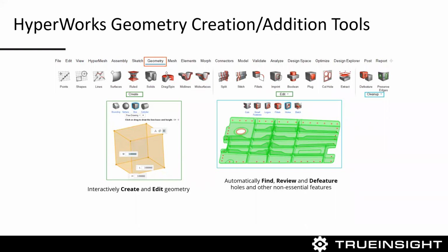In my own experience, I might have something like a wind turbine within a PLM system with a lot of subsystems. If I was not using HyperWorks, I would have to go back to my designer and ask them to make changes to pre-process that data. Within HyperWorks, we can do everything. For instance, if I want to remove holes, or remove logos, anything that's a geometry feature, I can adjust or edit it to repair. These would be things that you typically wouldn't model in most structural analysis, like a logo. That's not really going to change the stress or displacement in your application.